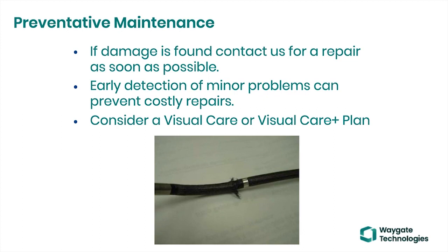And, you know, this is an area that will wear over time, and to get that braid and sheath changed is something that you'll want to do before it causes larger problems. Larger problems meaning if that bending neck becomes separated. I've seen people put electrical tape on them. I've seen them do a lot of unusual things, and then they put it into a work area, and the tape or this braiding gets bunched up, and you can't get the camera out of the inspection area.